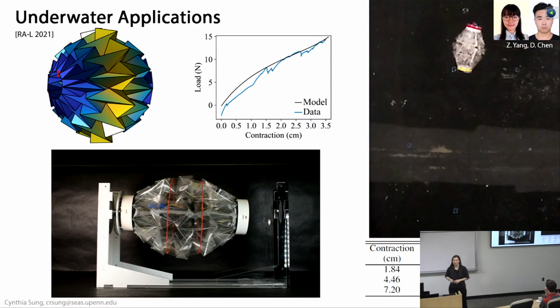Have you done any comparisons of this to more traditional materials like rubber? If you got a rubber device. Yeah, so this is a question we get a lot about, whether we've compared to other soft materials. We haven't done a formal comparison yet, but what we've found just anecdotally is that rubber is often much more dense, so it's heavier and much more damped. And so you lose a lot more energy into the material than you do if you use an origami structure. That's just anecdotes. We haven't done the formal analysis.